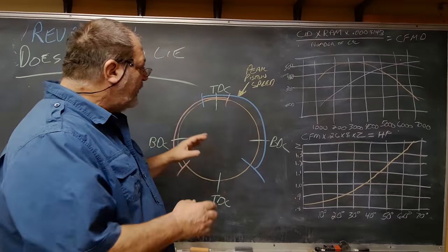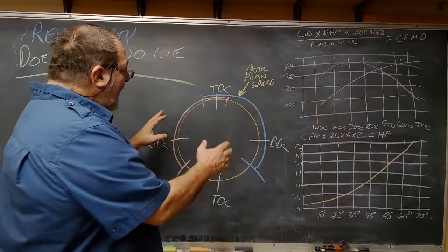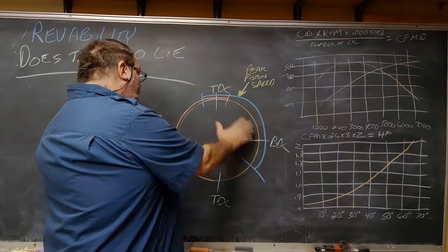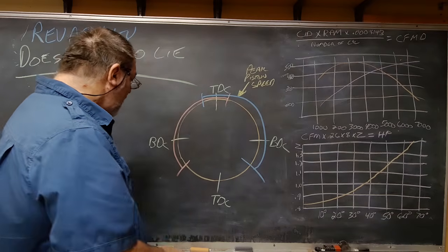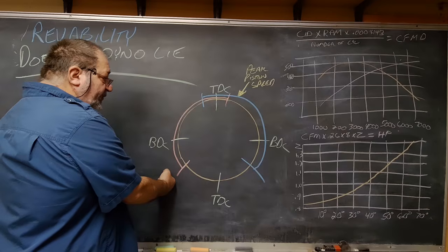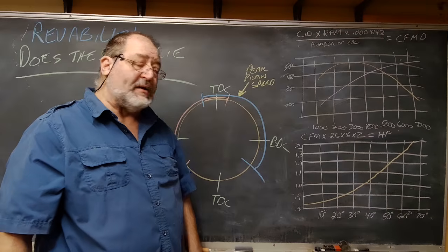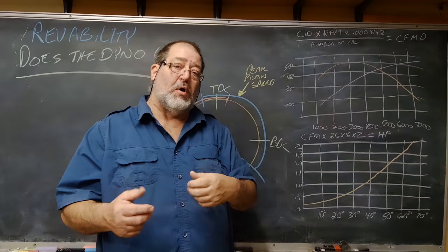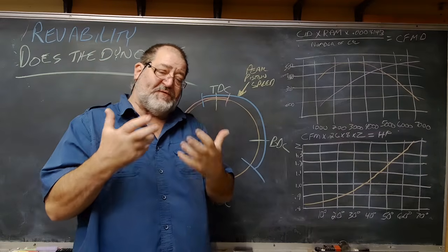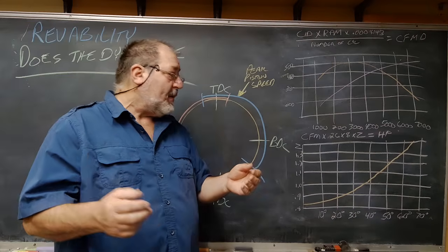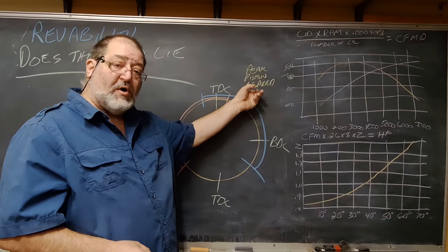So you may have to do what, if you watch what I do, this is why. I may spread the load center and then twist the cam into an advance to get rid of some of that overlap. Open that exhaust valve sooner and get a better fill at that peak piston speed, because that's what makes the motor want to go.